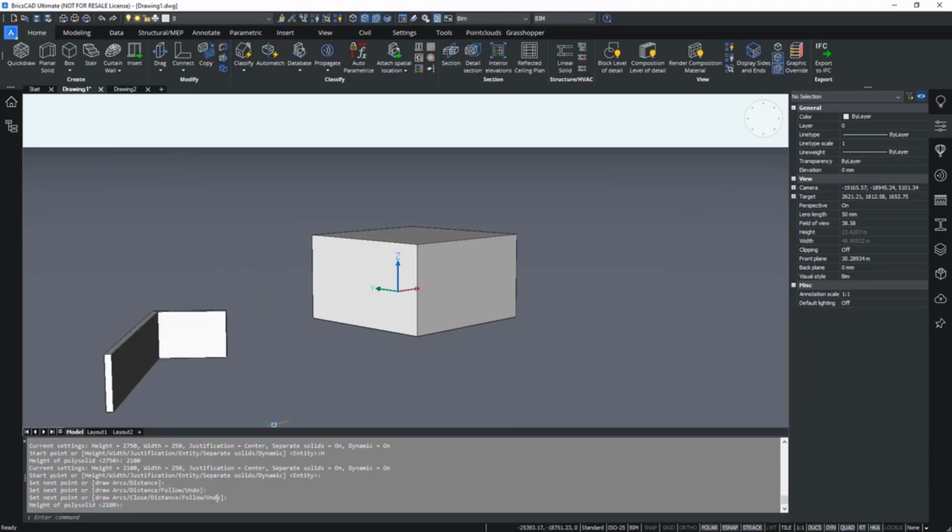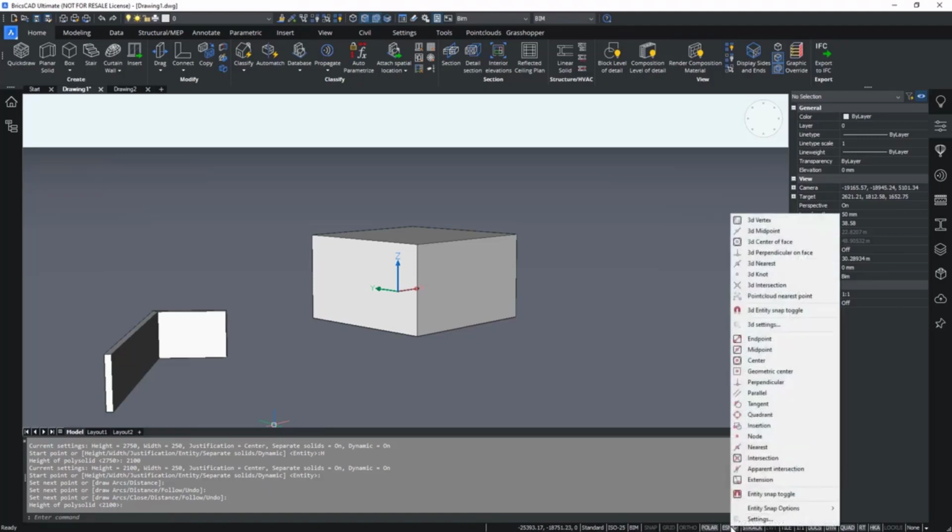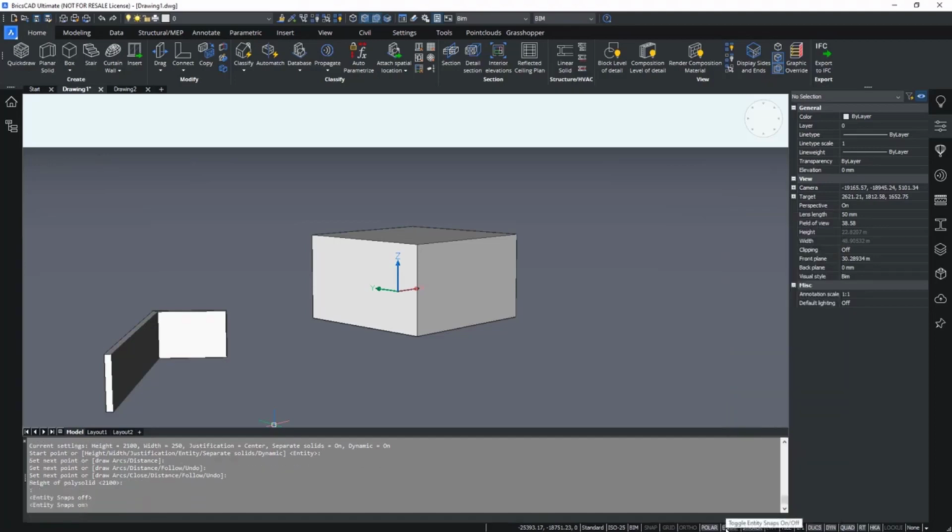And then finally, as we already briefly touched upon, is the status bar. There you can see that it's at the bottom of your BricsCAD application window, and it contains mainly info about settings which are on or off, such as the eSnap setting, which you can also right-click to see more, and you can toggle them easily by pressing them with a left click.